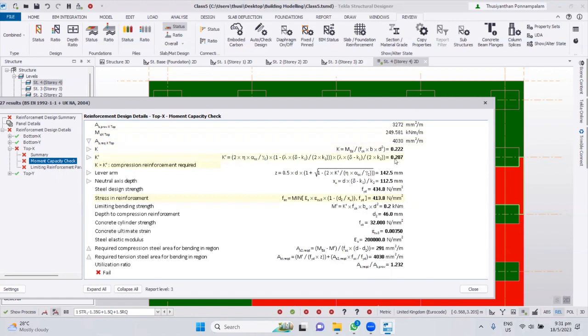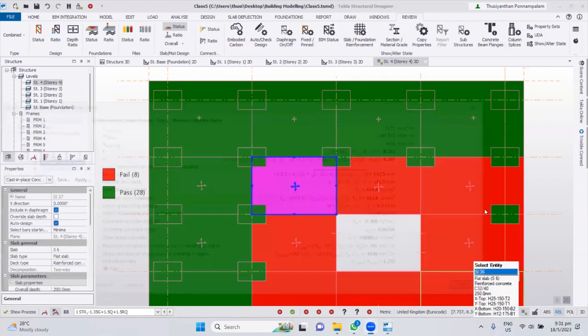The reason is we take the average, but this one is designed for peak moment. So if you go with the automated design, this is a disadvantage. You pick the peak moment and design for it, so sometimes you have to overprovide the rebar. That's why normally I do not recommend going with the automated design. It's always recommended to go with the strip method.